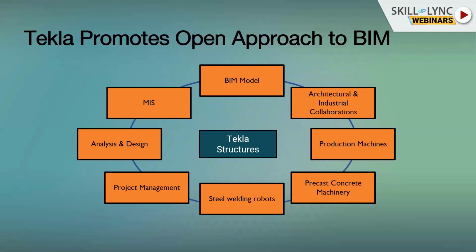Basically, nowadays we are also using CNC machines. When you're creating any TEKLA model, basically a steel model, you just export your NC files, and you put those files on your CNC machines, and the plate is automatically cut according to your requirement.